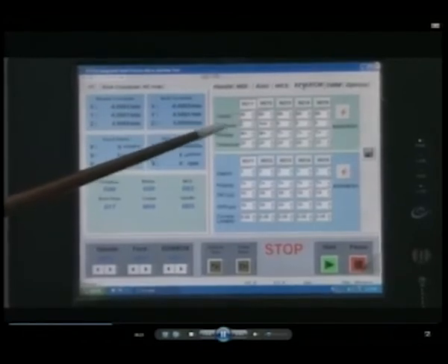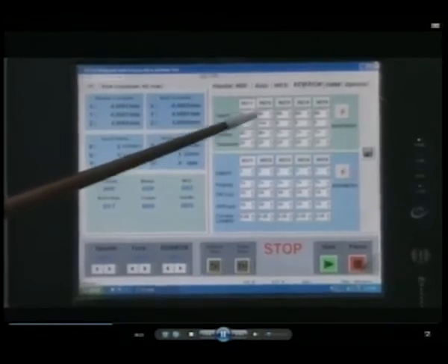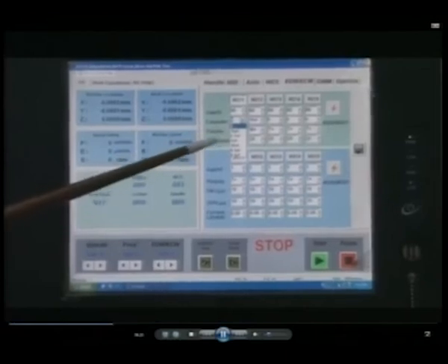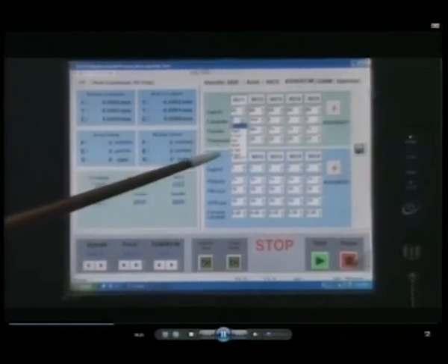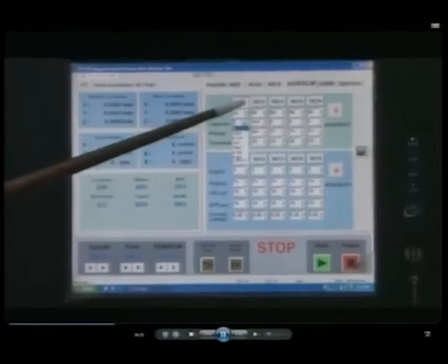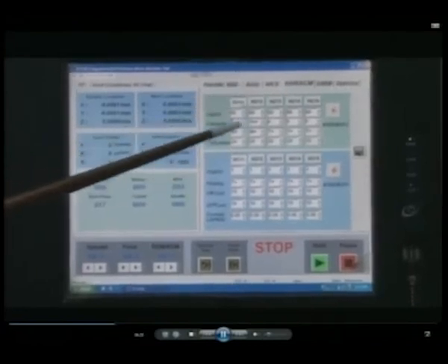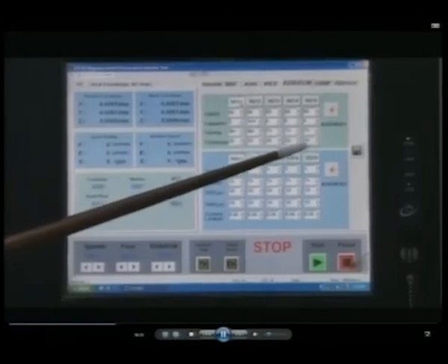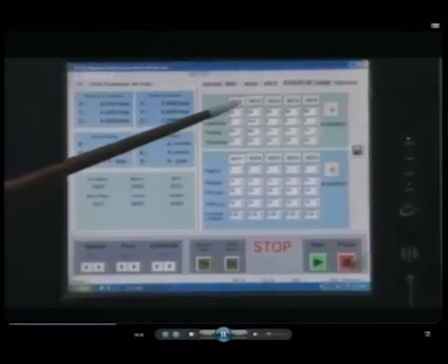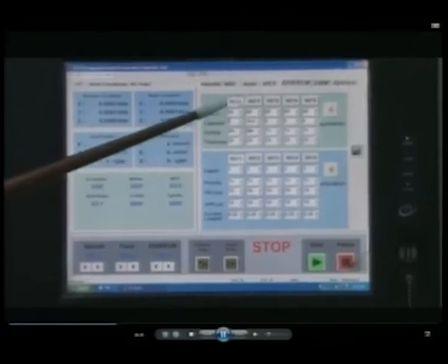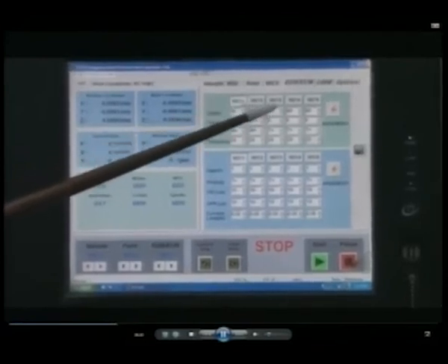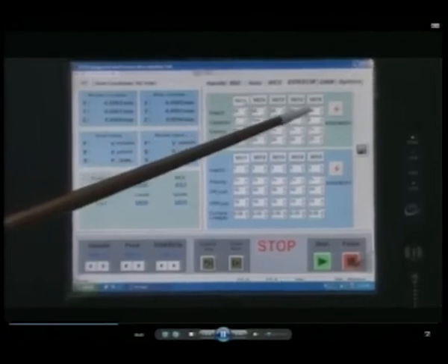The capacitance has different values, which can be 10 picofarad, 0.1 nanofarad, 1 nanofarad, 10 nanofarad, 0.1 microfarad, 0.4 microfarad. 5 different sets of parameters can be set simultaneously and called in the program. These are represented by M codes, which are M211, M212, M213, M214, M215.